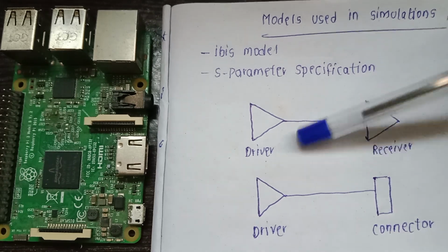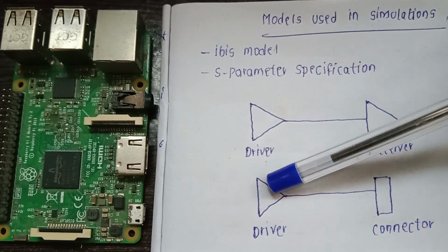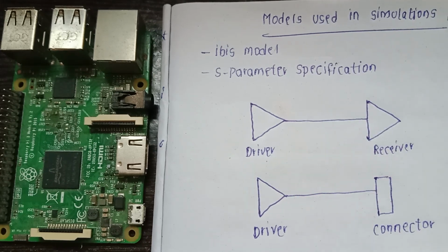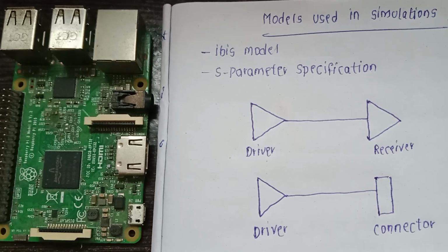That is scenario 1, and then scenario 2: a driver sending a signal to a connector. On our boards there can be two ICs between which communication happens. For example, in Ethernet communication, such as SGMII, we have communication between the processor and the Ethernet PHY, MAC to PHY, which is a differential communication between two chips.